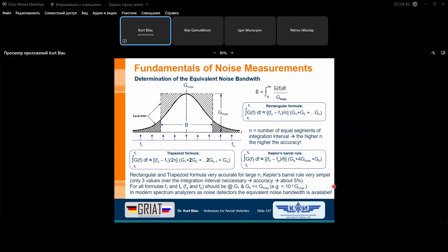A radome can prevent atmospheric influences on the antenna. But a lot of antennas are made from aluminum. Aluminum has a lower conductivity than copper and than silver, but in a lot of cases it's sufficient to realize the antenna with aluminum. And aluminum has a high resistance against influences from the atmosphere, weather, rain, and so on.